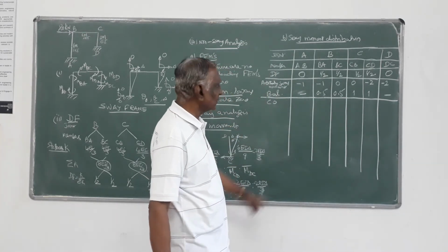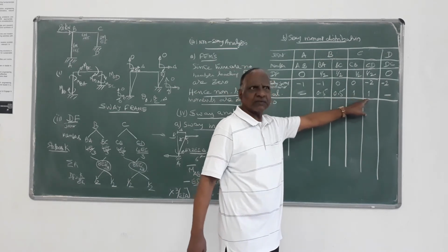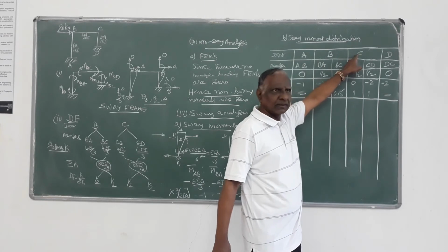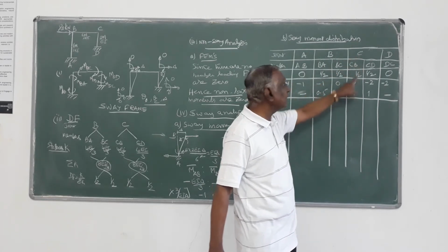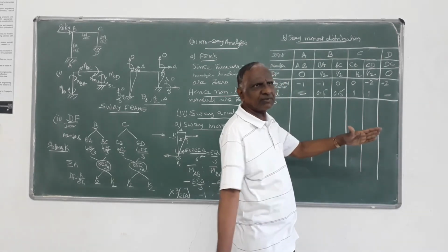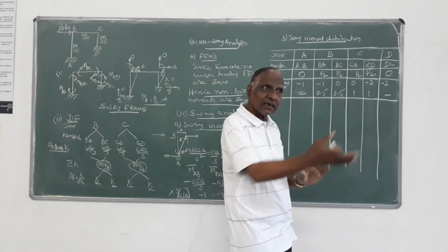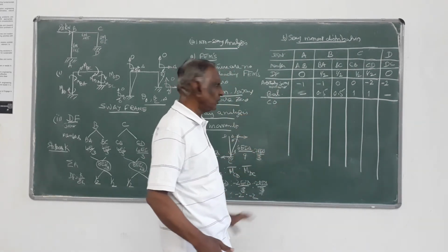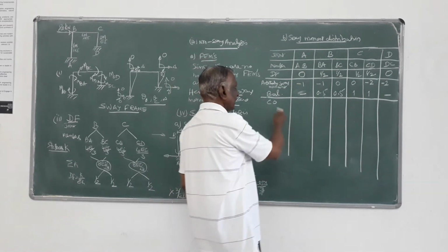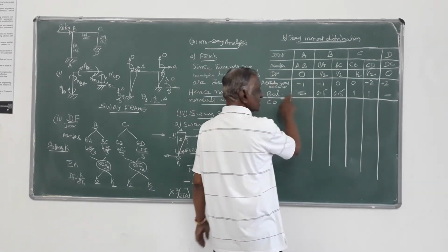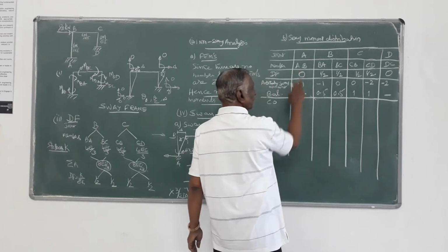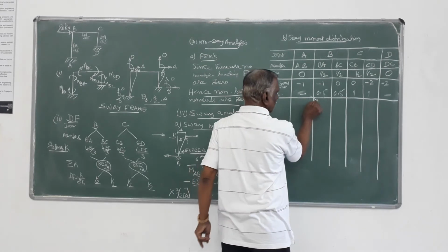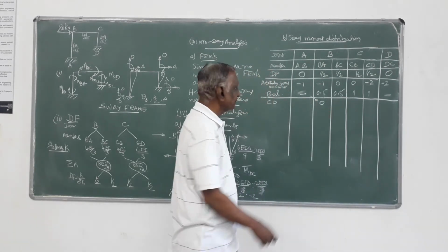Next we will go for cycle 2, because these balance moments that are there in the members are coming from one end. In the member CB, this is the balance moment coming from C. It will have an effect at the D end of the member, that we call the carryover. That effect is half of that particular value, so we will carry over for each. For AB, there is no balance, so no question of any moment transferring from AB to BA end. So here it is 0.